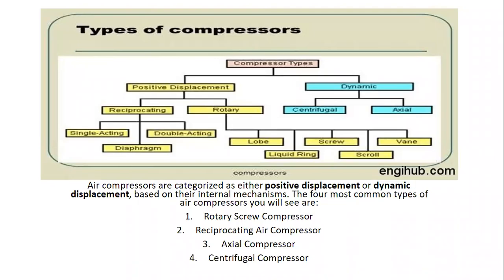Also, the liquid ring and scroll compressor, while the dynamic compressor is divided into centrifugal and axial compressor. All right, air compressors are categorized as either positive displacement or dynamic displacement based on their internal mechanism.